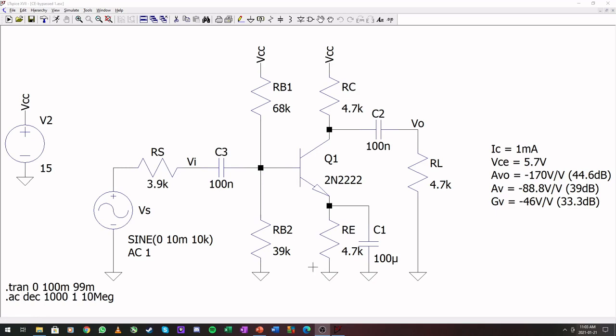So to increase the input range of an amplifier, adding the emitter resistor is also a good thing for that. Right, but we will look at how to calculate that in a different video. Same with maximum output swing and how it relates back with linearity. This is just more about analyzing for our gains.